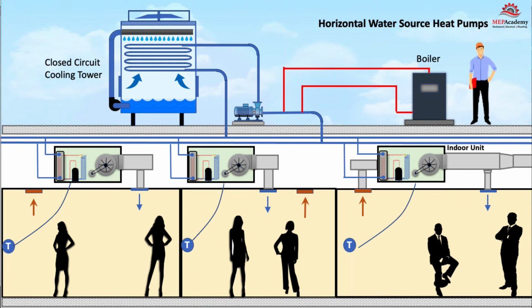Various commercial buildings will have concealed horizontal water source heat pumps installed for each zone or room. These may also be found in hotel guest rooms, usually mounted above the entrance or bathroom with a stub of duct to feed a supply grill with a ceiling-mounted return grill. The return grill could also contain a filter. These units are also available for exposed locations, usually near an exterior wall, to provide a method for fresh air. Just like the vertical stacked heat pumps, these horizontal heat pumps will have a closed-circuit cooling tower mounted outside.